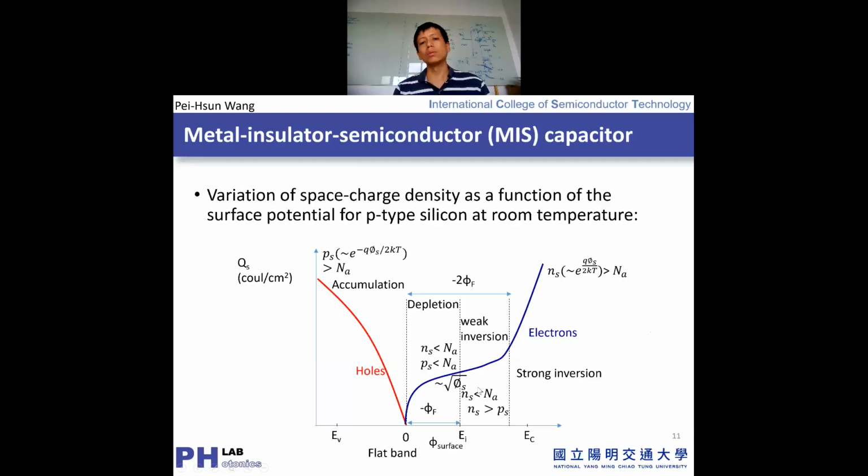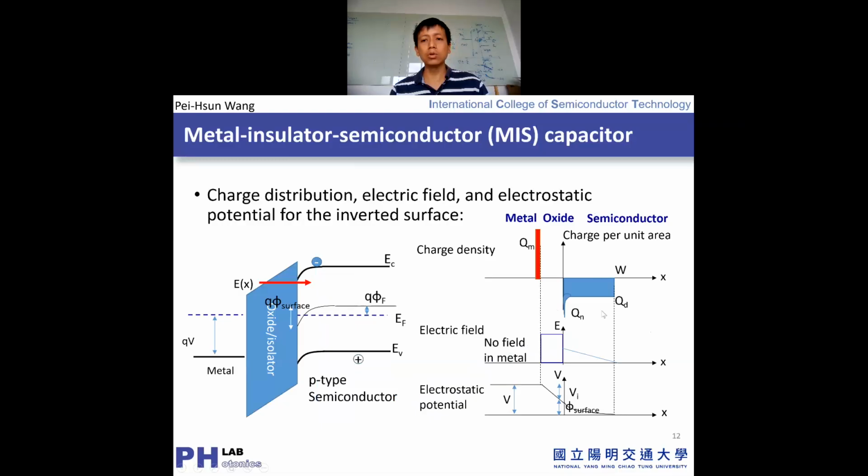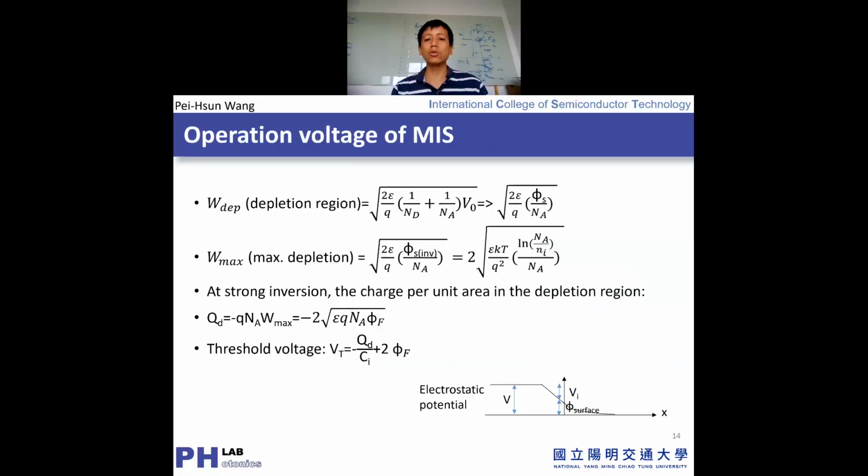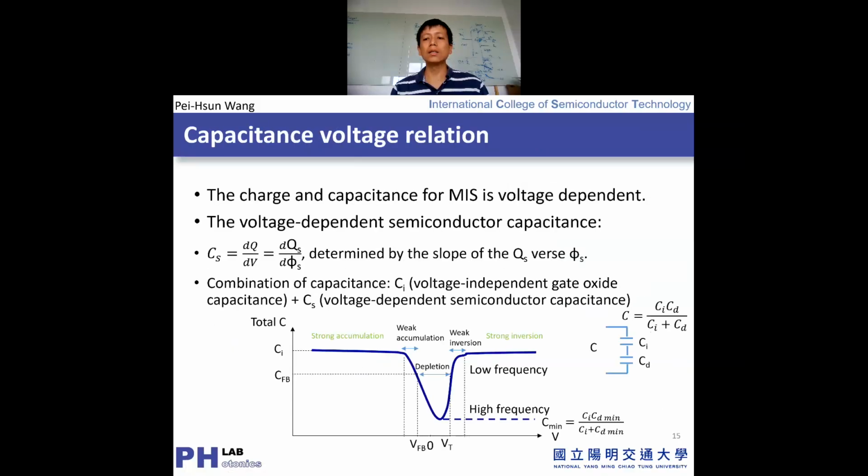But if you work with the inversion or depletion regions, we get the change of charge from hole to electron. So under that condition, you also get the distribution of the electron, which is related to the dielectric constant in the semiconductor and also the depletion distance over the W. And then we can judge this value based on CS or CD.